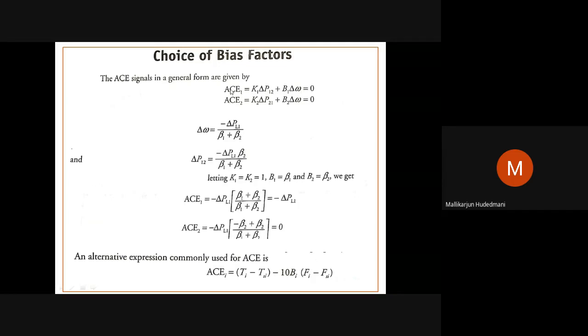Because ACE 1 is 0, the controlling area 1 is in steady state. It means ACE is not causing any stimulus to the integral controller. Whatever speed set point was already set earlier is working fine. That is what we can view from this.